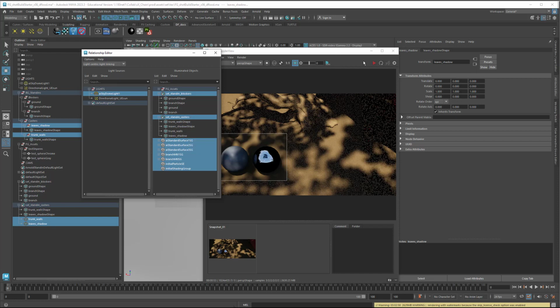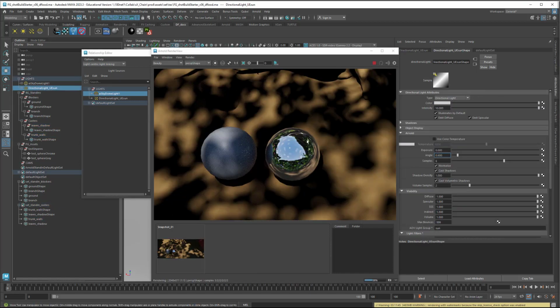And now if I re-render, you can see that we have our HDR sphere, everything reflecting nicely in the chrome ball, and including that we've gotten the shadow casting leaves out of the frame. And now that's everything that we're going to do globally for all of the stand-ins, but there's a couple things we want to do for each individual stand-in group. One of them is on the gobos or shadow casters, is that we want to turn off primary visibility.